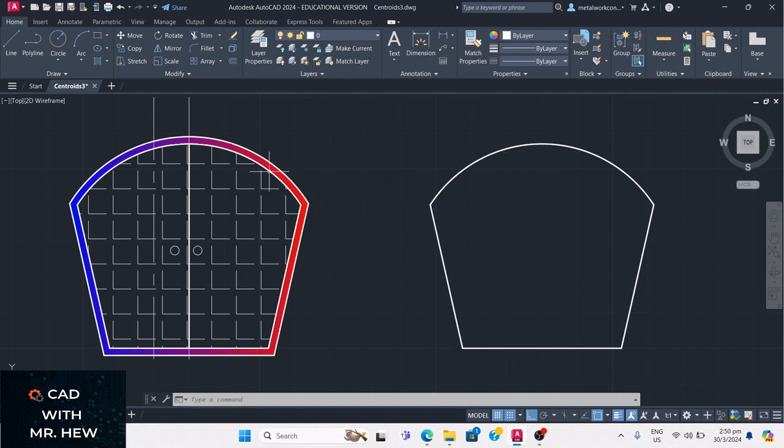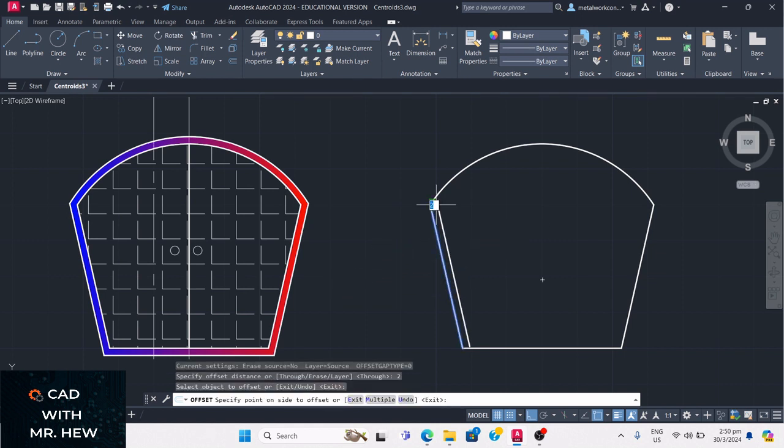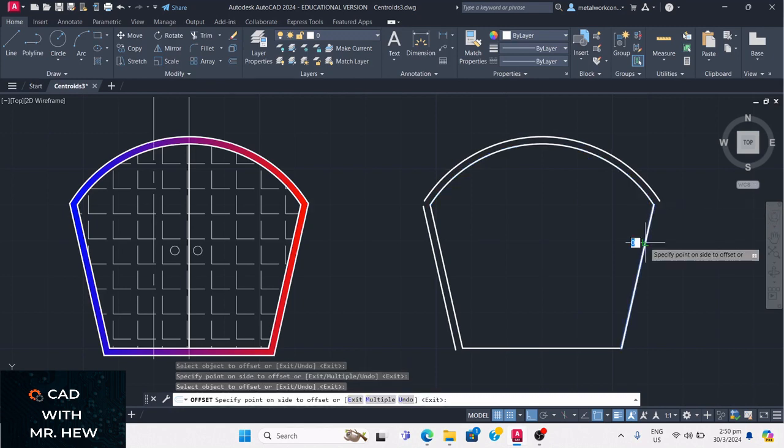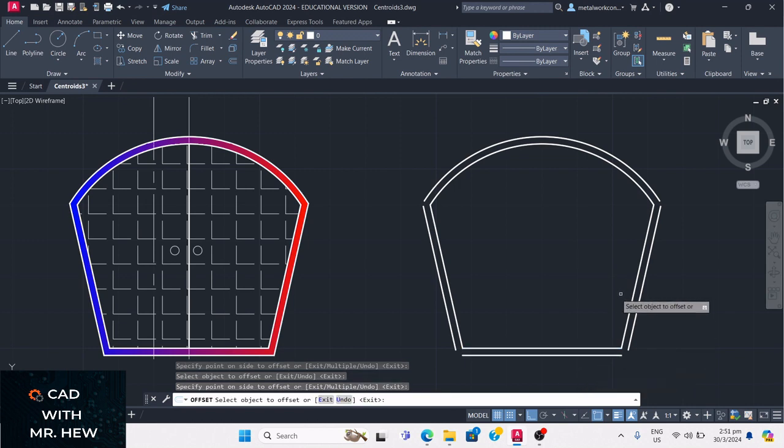What I'm gonna do is draw the outer one now. We're gonna use the offset command. So this is offset. Here we click on it and it says specify the distance. So we are in millimeters. So I'm gonna put 2 millimeters. And here we offset there, there, there, there. Then enter. We're gonna use the fillet command now to close the thing.